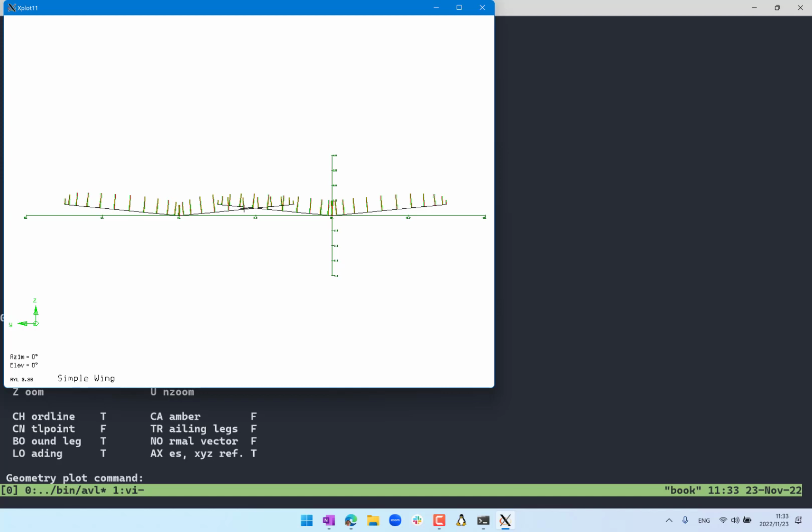and you see the loading on this is the starboard side of the airplane, right? Because we are looking from the front. So this side of the loading versus this side of the loading is very different. The loading is pretty much uniform on most of the wing except for at the tip. But over here, the loading is high and suddenly goes down over here, right?